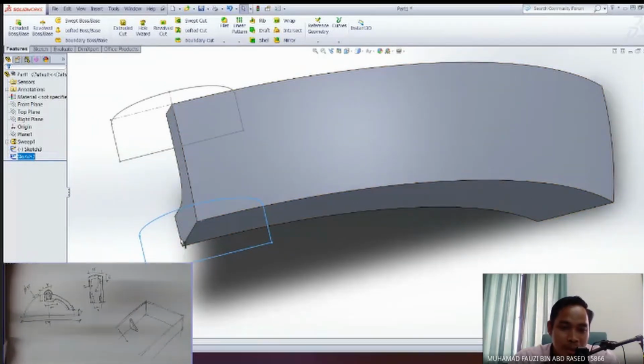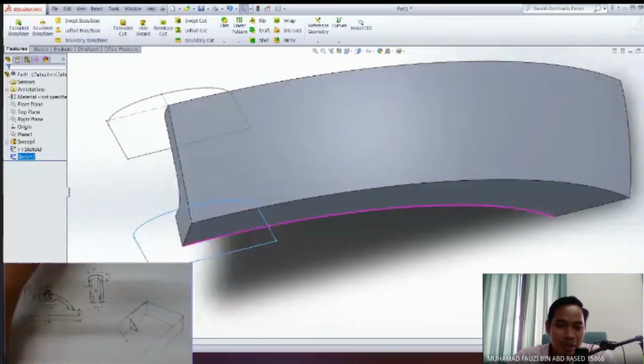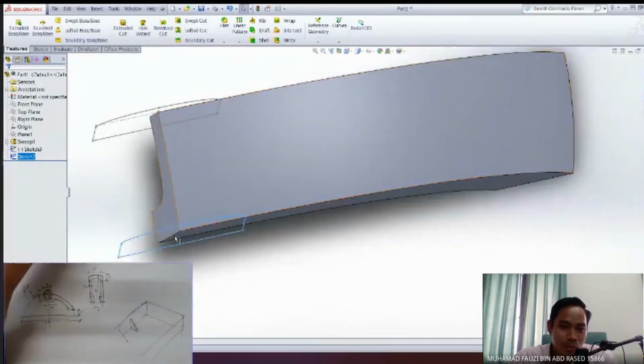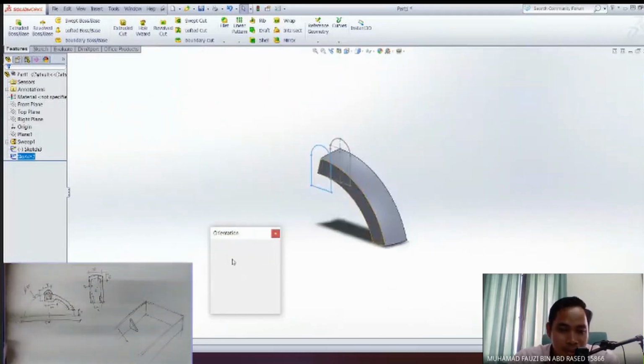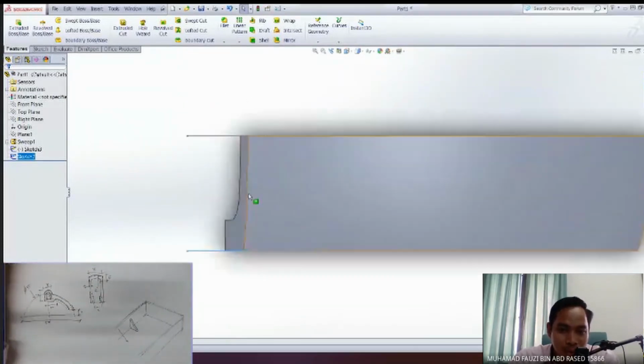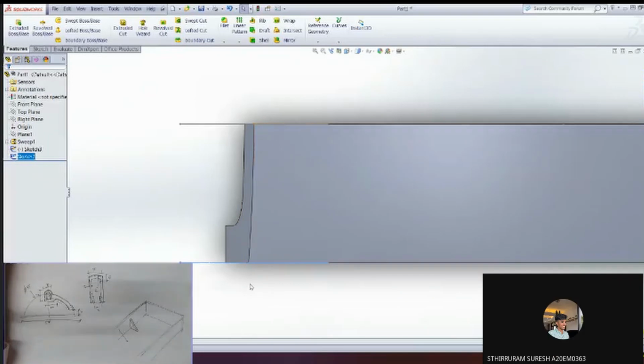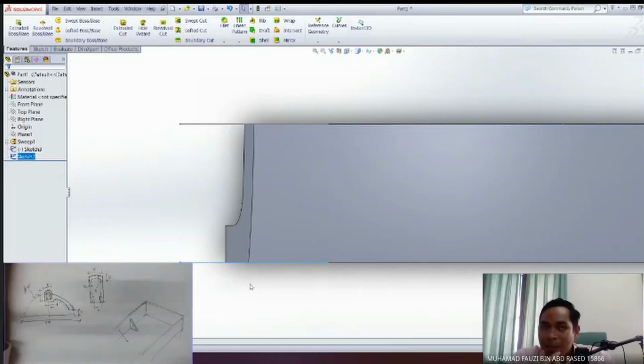before this I copied and pasted, and then I made a constraint to this point. Actually, this one is a little bit away from the location. It's supposed to be on this line. So this is the thing that you need to take care of. It's best advised not to copy and paste; we have to use the features in the sketch mode, depending on the plane that you want to use. If it's not really important, then it's okay.